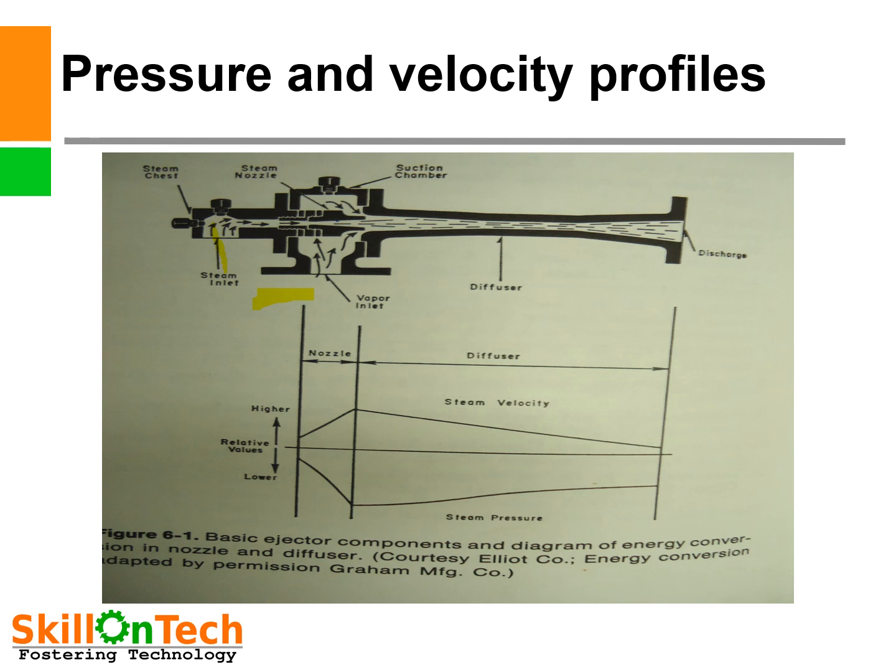the area of the ejector diffuser is getting enlarged. So again the velocity energy will convert into pressure energy, and a little pressure will be gained again in the diffuser as the cross-sectional area of this diffuser is getting increased.